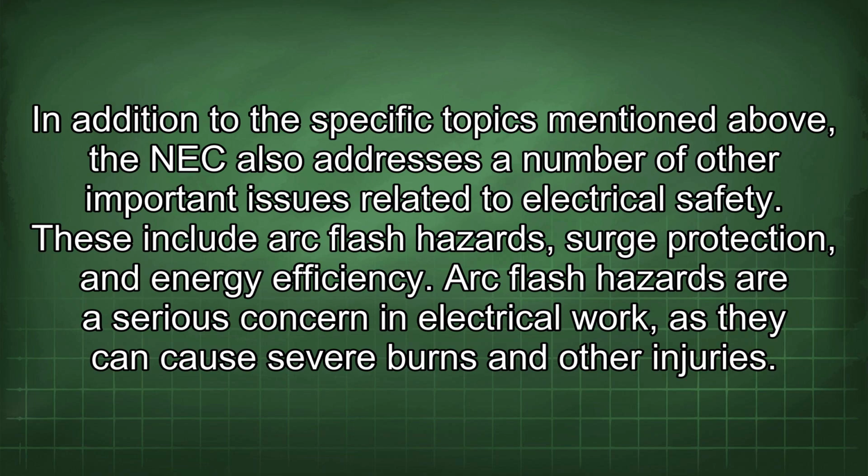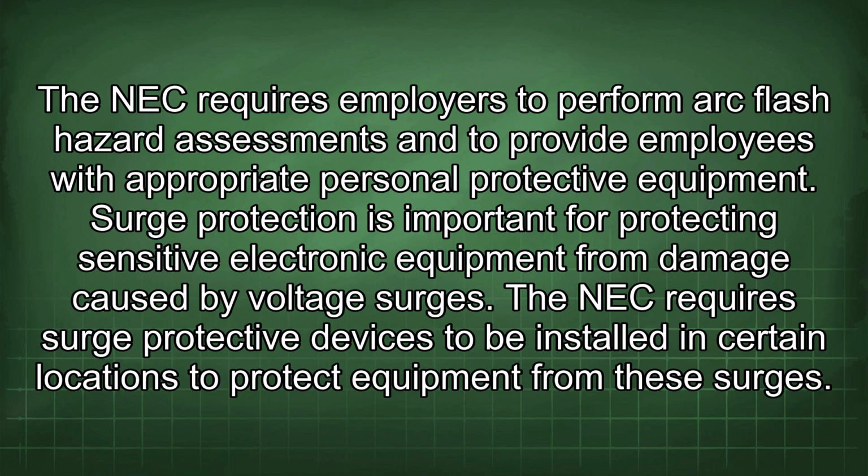In addition to the specific topics mentioned above, the NEC also addresses a number of other important issues related to electrical safety. These include arc flash hazards, surge protection, and energy efficiency. Arc flash hazards are a serious concern in electrical work, as they can cause severe burns and other injuries. The NEC requires employers to perform arc flash hazard assessment and to provide employees with appropriate personal protective equipment.